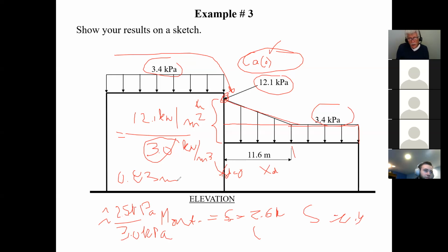Even though the snow loads they give you to do these calculations are reasonable, you never know what nature is going to throw at you. So if you start seeing snow loads over 4 feet, in other words about 1.2 meters, especially in Montreal, anything over a meter, and it's just January, it's going to keep on snowing until the end of March, maybe the beginning of April. So the prudent thing to do is to go up and remove the snow.